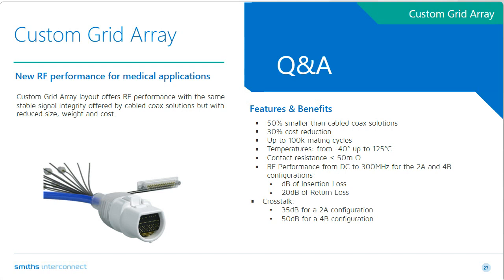Sure, thanks for that question. Yes, grid arrays are used in many different applications. Smiths has catered to quite a few of them. In particular, we've served applications in interposer and backplane markets and semiconductor test solutions that can guarantee a high level of performance encompassing frequency ranges from 0 to 70 gigahertz. And that would also include the 112 gigabit per second PAM4 data rates in some instances. So I believe that, yes, with the grid array solutions, you can achieve quite a bit of signal integrity performance.